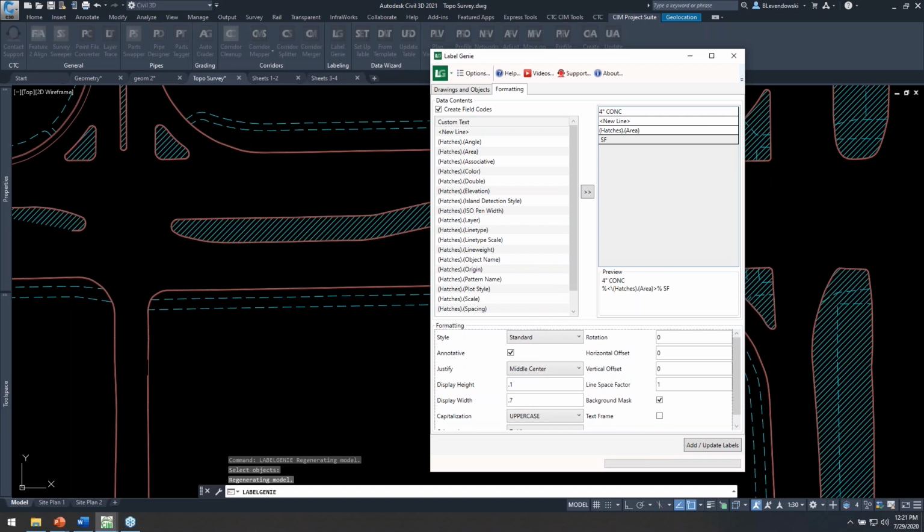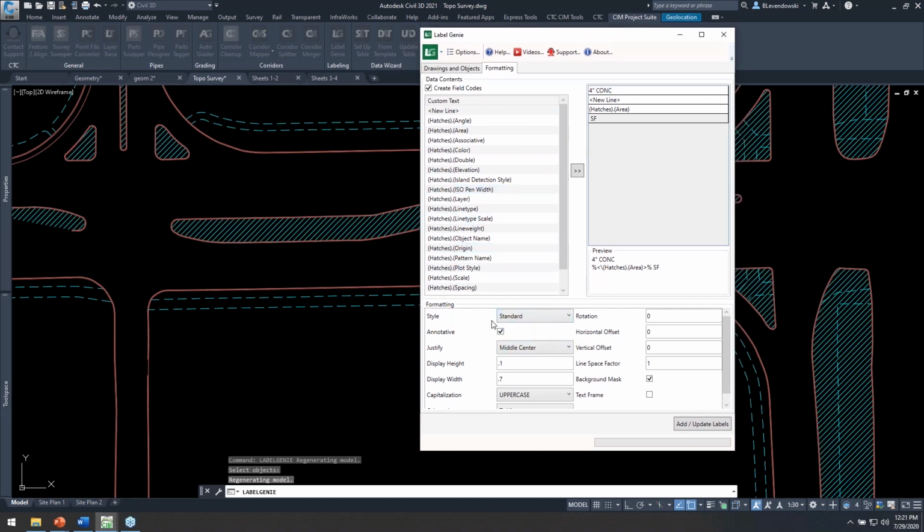Coming down here, because it's Mtext, there's a lot of formatting options, right? Civil 3D styles, you have a lot of that stuff built in the style. But when it's Mtext, it's basically defining the font, some obliquing, and just a few things, right? So we give you all those options in here. What's your style, your text style to choose from? Is it annotative? What's the justification?